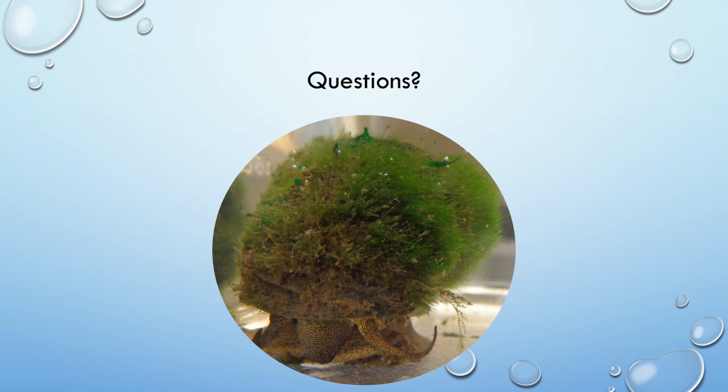Okay, so is there a way to differentiate the BOD released from sludge from the incoming BOD? Possibly. So you might have your influent BOD numbers in the liquid, and you might be able to take a sludge sample and approximate the BOD in that, or take water off of maybe a foot above the surface of your sediment layer and see what that BOD comes out to and compare the two. And it might be higher or lower depending on where you took your influent or incoming BOD levels from.